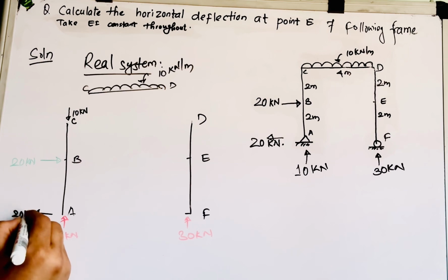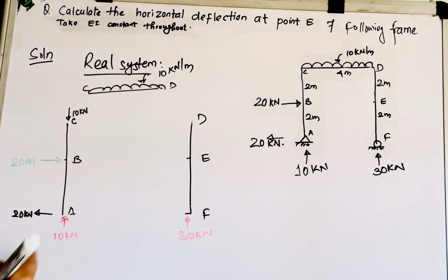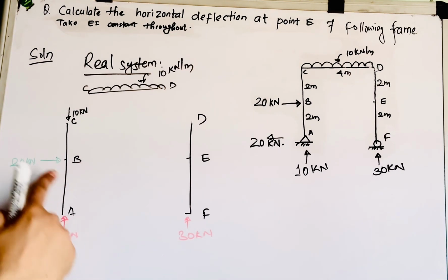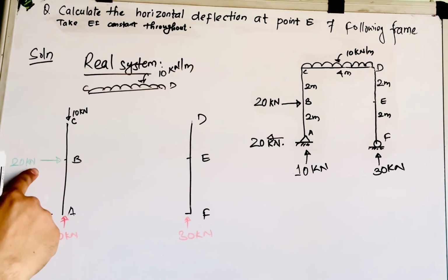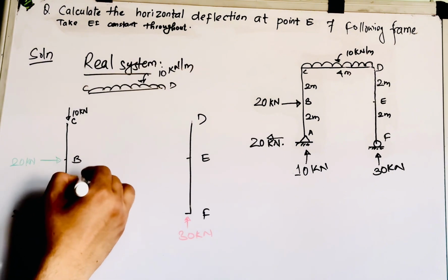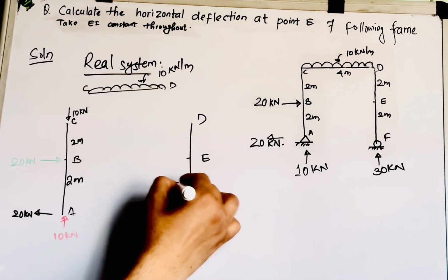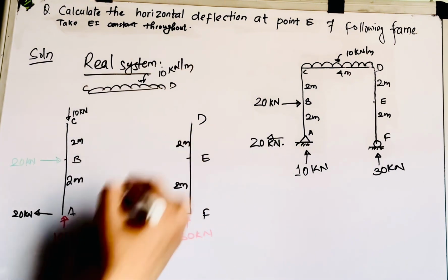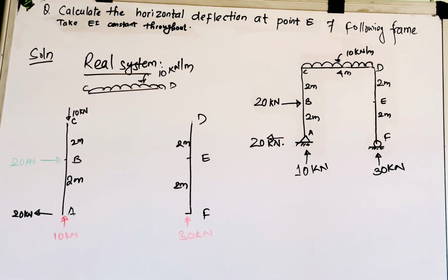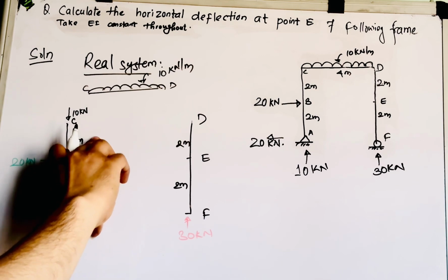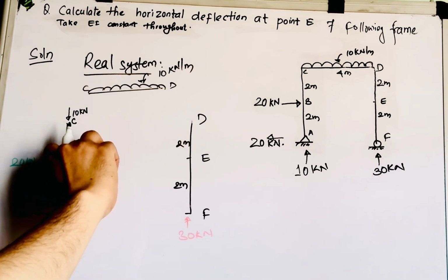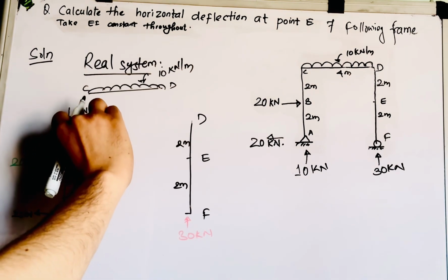This is the reaction force that developed at the hinge support, right? So 20 is balanced by 20, shear is balanced, axial is balanced. Now you have to determine the moment that develops at point C or joint C of this member. So let us say 20 kilonewton into 4 is what? 80 minus 20 into 2, that is 40.